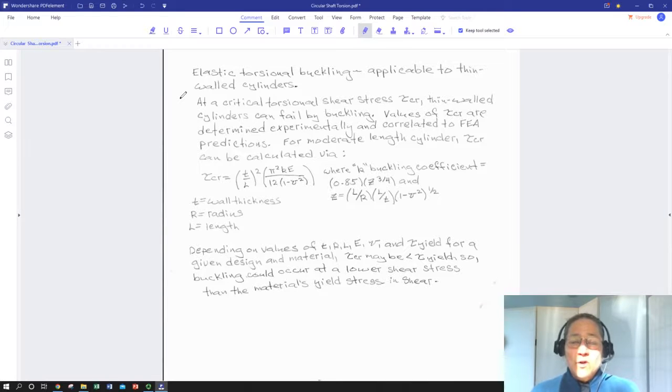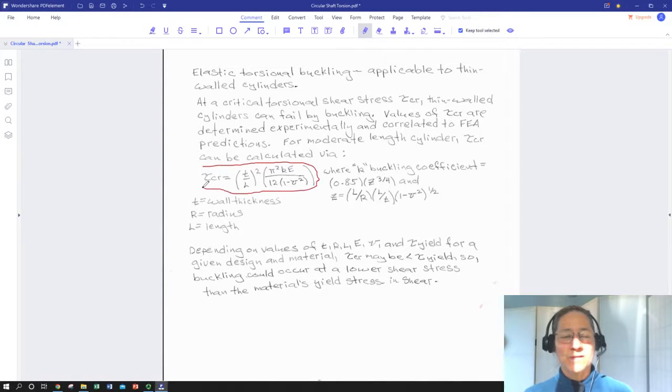So this is another one of those limits to check, and it's determined more or less empirically, and we can use all of that test data to come up with an expression for the maximum shear stress. Of course, we're going to be measuring that out on the outer radius, where we would have to worry about a tubular shaft crumpling or buckling as we twist it.